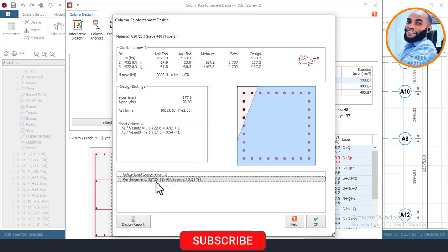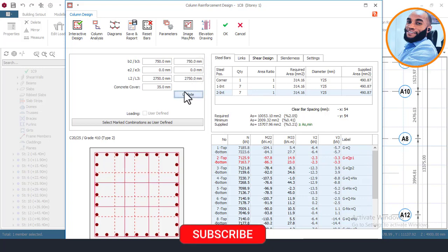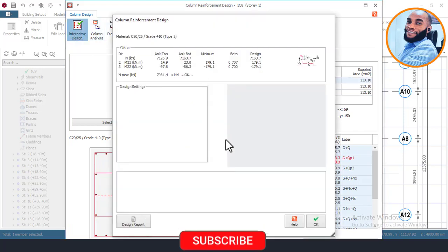Okay, right now it is okay, but basically I don't want to use a 700 column. I want to use a column width of 750 by 750. I want to use the conventional one, and I'll say update here. So basically 700 was okay to carry the load, but I just want to choose 750 and all that. Okay, so I'll reset bar first, and then design all that.